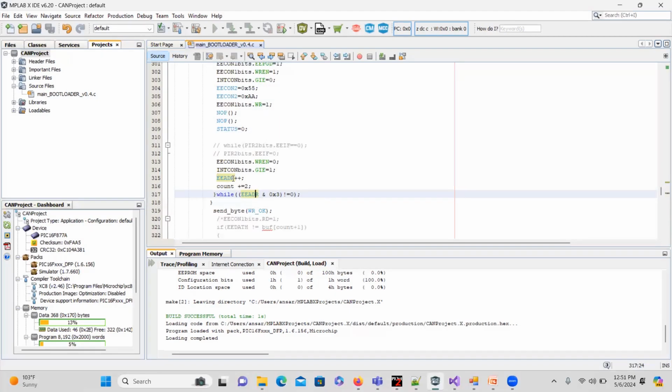When the address becomes 3, ANDing it with 3, you will get 3, which is greater than 0. Again, we will go for it. So when we reach the 4th byte, that is 1 0 0, we will get 0 here. The result will be 0. When it is 0, we come out from this batch writing and we go for the next batch.